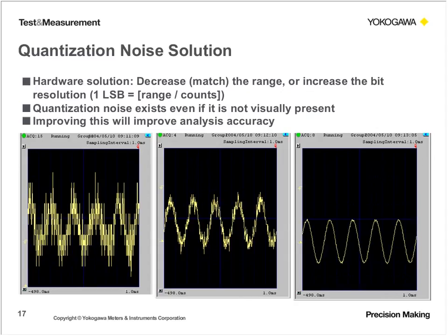So you may be asking, what's a better solution? Well, we want to do one of two things. The first thing, from a hardware perspective, is you want to decrease the dynamic range, and that will increase the bit resolution. By lowering the range from -10 to 10 volts, let's say you reduce it down to -2 volts to 2 volts, that will essentially increase the resolution so that you can measure much smaller changes. Maybe instead of 78 millivolts, now you can measure down to maybe 10 to 20 millivolts.